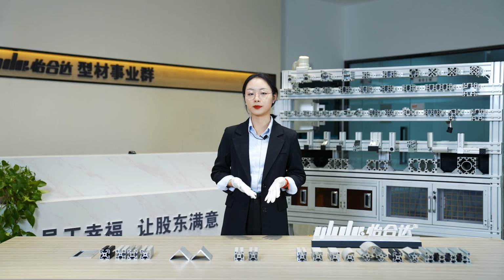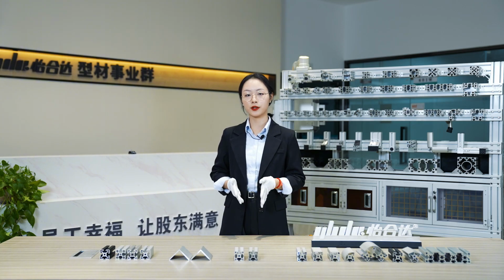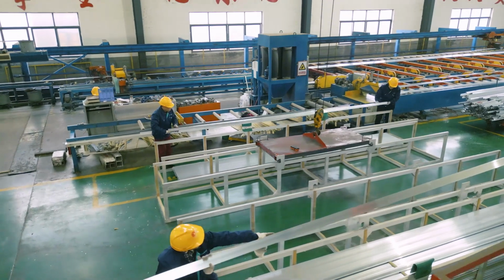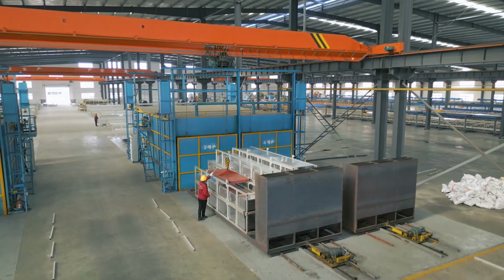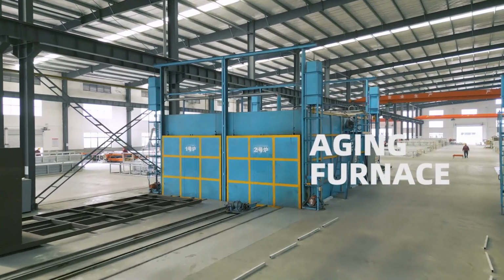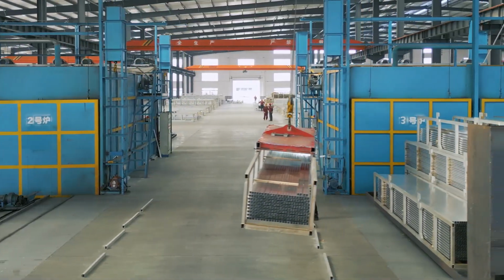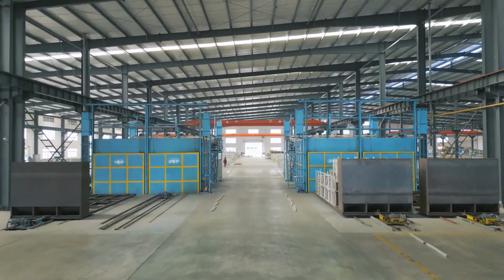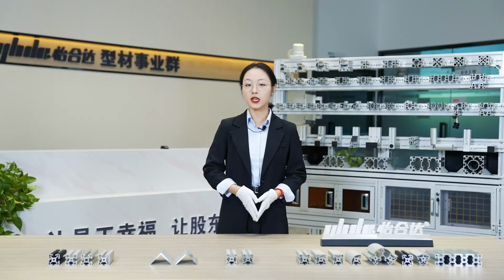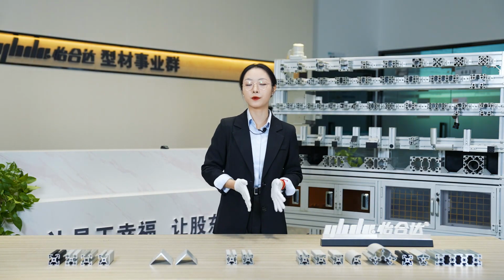At this step, customization of joints is also possible to fully meet various shape requirements. After straightening, the aluminum profiles undergo an aging treatment. Typically, they are held at a high temperature for a period of time before cooling to improve performance and stabilize microstructure. There are usually 2 types of aging treatment for aluminum profiles.